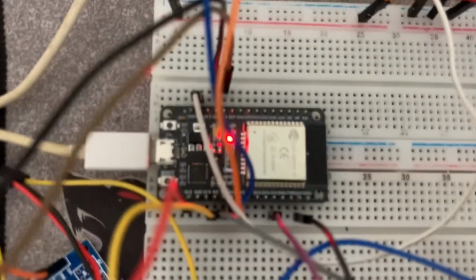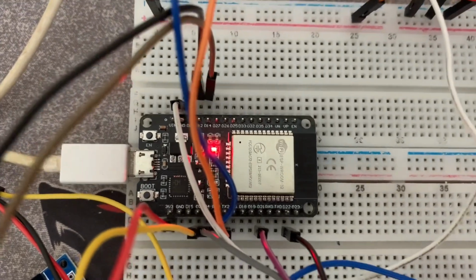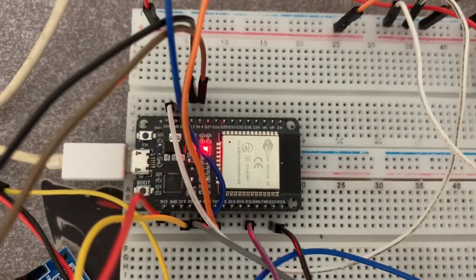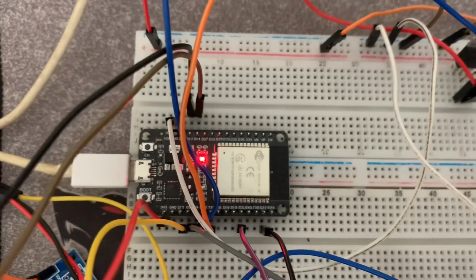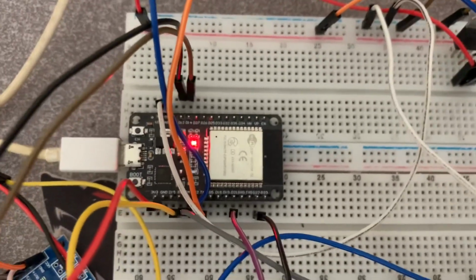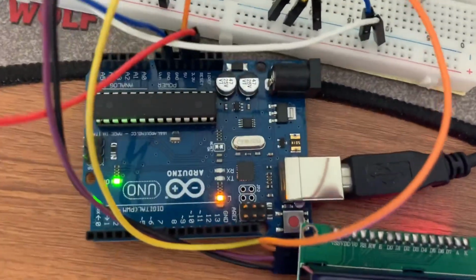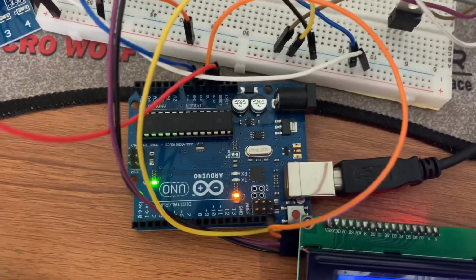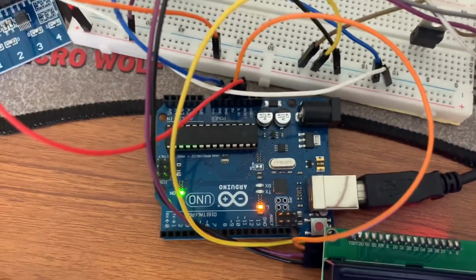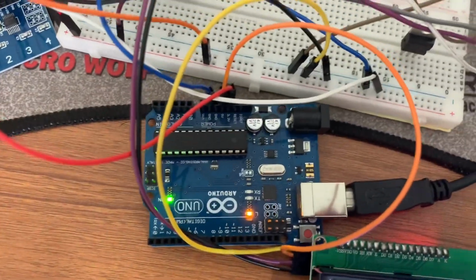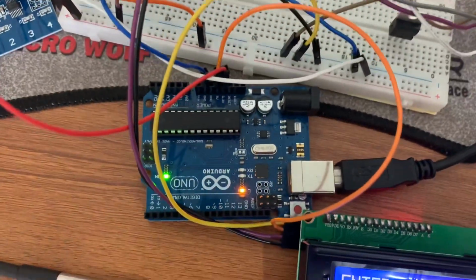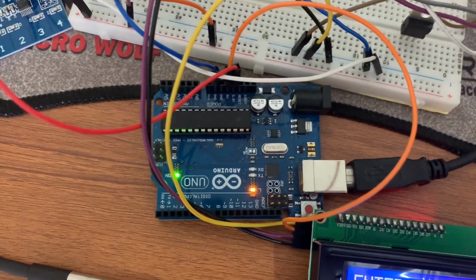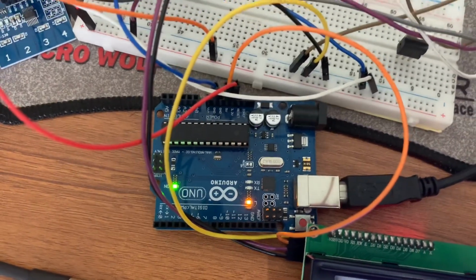As the microcontroller, I have used the ESP32 board, which has onboard built-in Wi-Fi that will allow me to send all the health parameters as well as room parameters to a dynamic web server, as well as to send an alert by email. I have another microcontroller here, the Arduino Uno board, but I haven't used it to compile my project. Rather, it's only been used as part of the power supply. I will tell you shortly the number of sensors that I have and the supplies I have provided to power up the sensors.